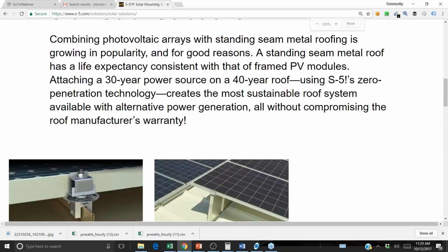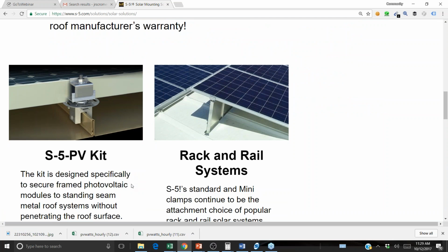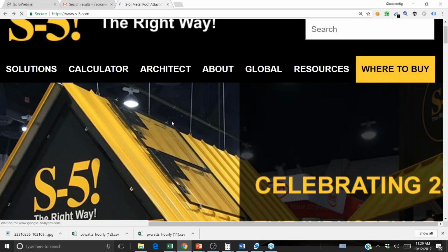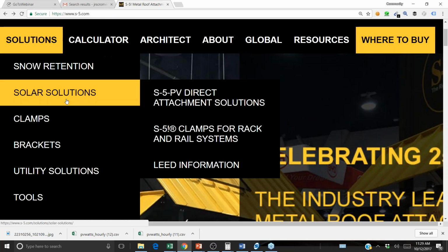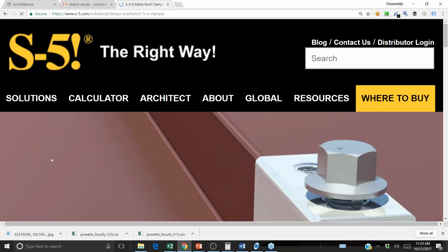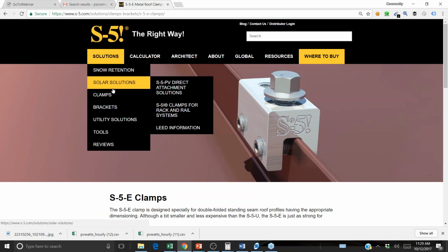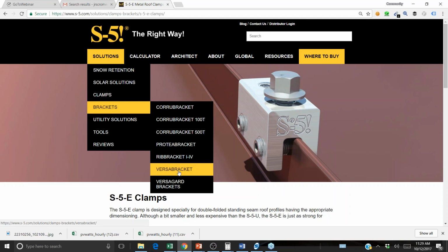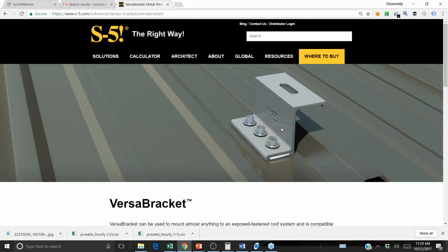So you might need to penetrate the roof anyway. But also, when I do metal rooftops, you don't always have that standing seam. So in another class, we highlight this corrugated metal roofing bracket where you're actually going into the metal roof, with the context that these solar attachments are designed to penetrate the rooftop in a waterproof manner, and that solar is not the only thing that pokes a hole in the rooftop.